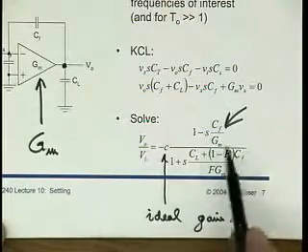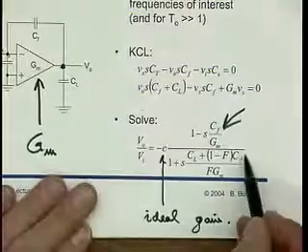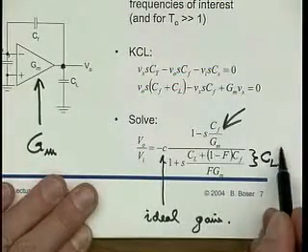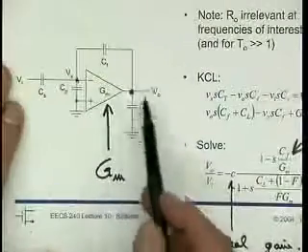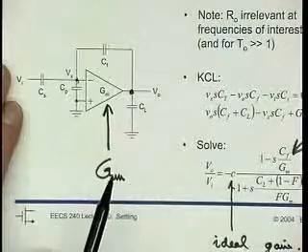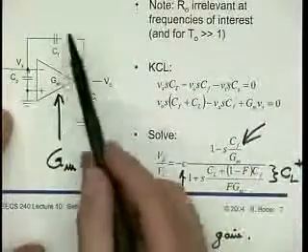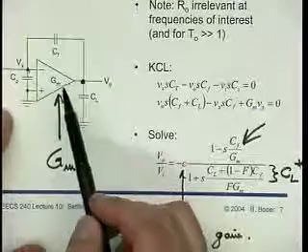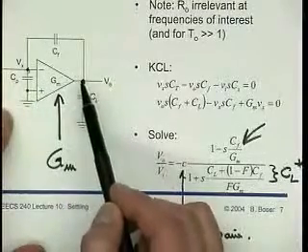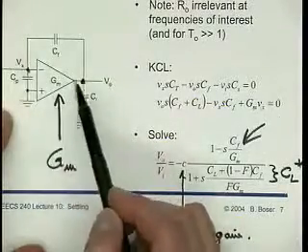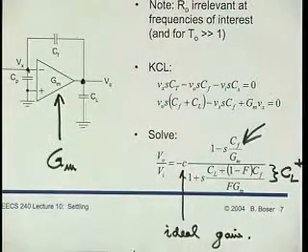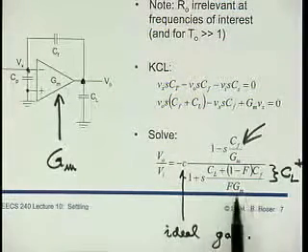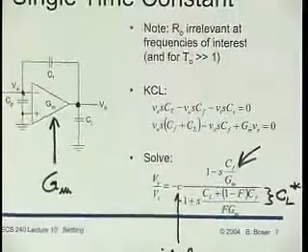And then here, this thing we have seen already before. That's this CL star, right? We don't see only the load capacitor here, but we also see a fraction of the feedback network, specifically of this feedback capacitor, and the fraction that we see is determined by the Miller gain around this capacitor CF. And this Miller gain is 1 minus the feedback factor. So it makes perfect sense. And then here we have the transconductors.